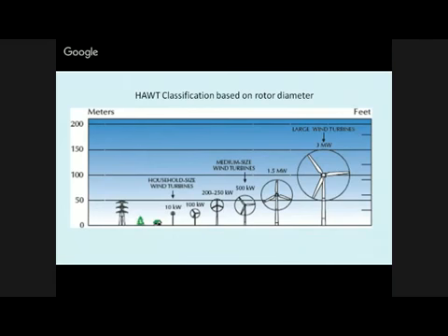And big-sized wind turbines, the large wind turbines, are those whose order of magnitude is megawatts. At present, particularly in Rajasthan, Jaisalmer, they are using 2 megawatt. In Gujarat also, Inox and Siemens are producing 2 megawatt capacity wind turbines. So as far as big size wind turbines are concerned, horizontal axis wind turbines are well developed, and this design is well saturated and almost at commercial level. In most parts of the world they are used for installations to generate electricity.